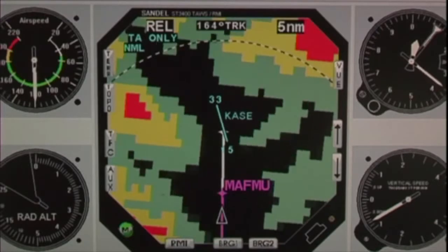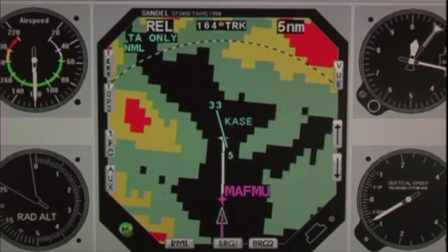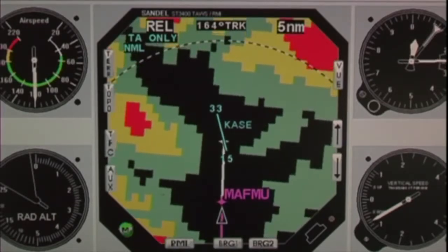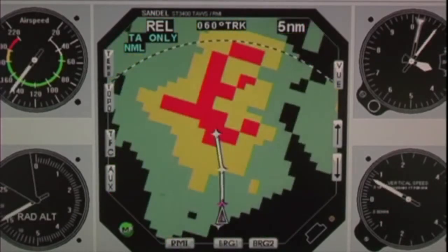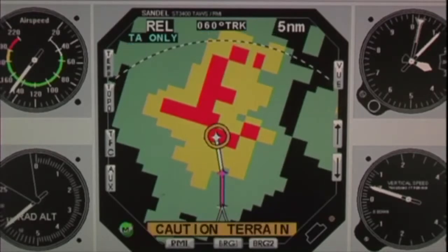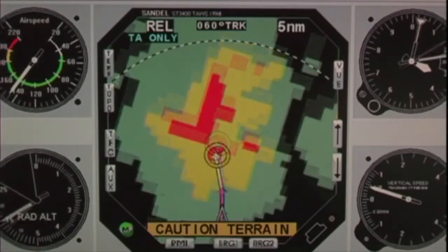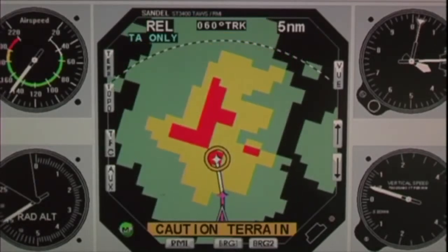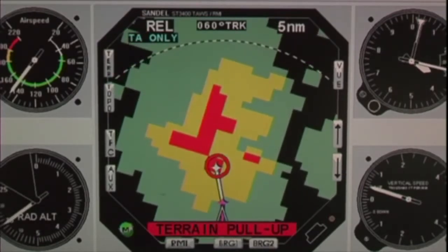Class C equipment does not meet the standards of the TAWS mandate, TSO C151B. Those of you who haven't flown with a TAWS yet will see that most TAWS terrain maps show the highest terrain altitude in red, with yellow used to show the less threatening terrain and green showing the location of the lower terrain. When a CFIT threat is detected, it's easily identifiable on the TAWS display. The 60-second caution alert is accompanied by a 7-point hollow star highlighting the terrain threat you need to avoid. At 30 seconds from impact, the yellow star turns red, and the approach visual and audio warning alerts are triggered, and none of us want to hear that.